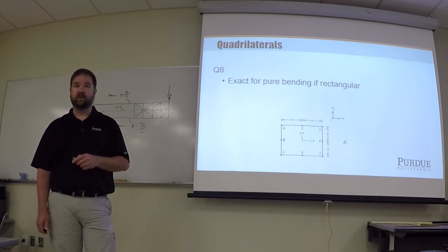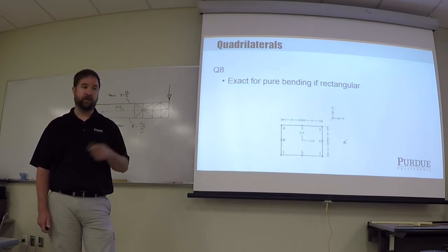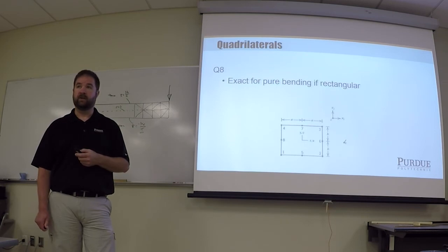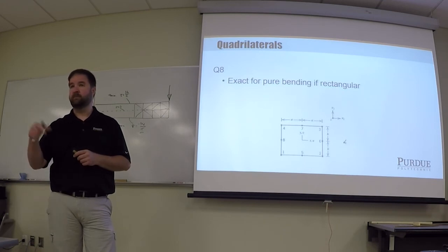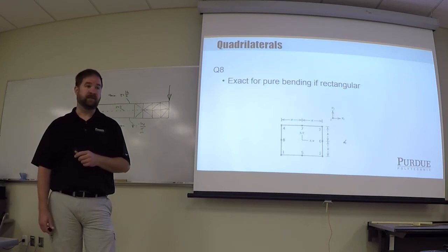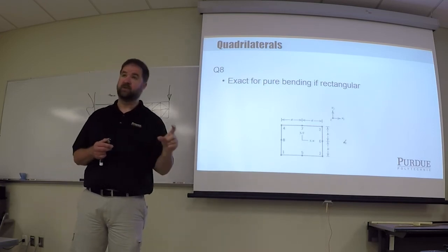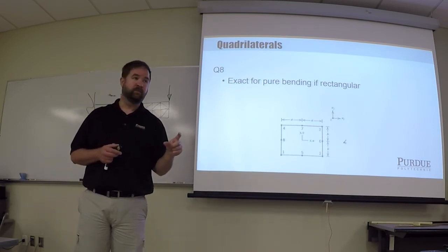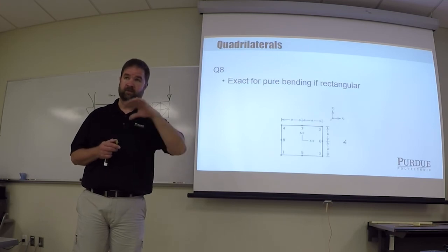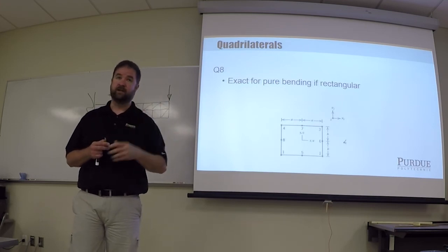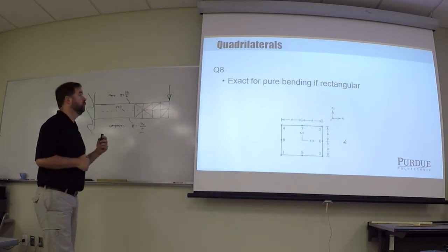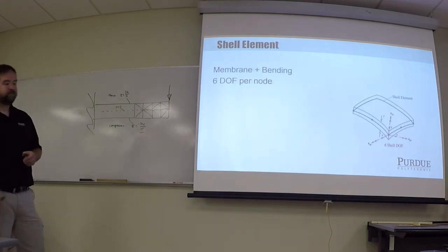You guys have probably done some of that when we do the 3D printing, right? You save your file as an STL. When you save it as an STL file, it takes all the surfaces and makes them into little triangles, right? Okay, we're doing kind of the same kind of thing: we're taking a surface or a shape and dividing it into triangles. Okay.